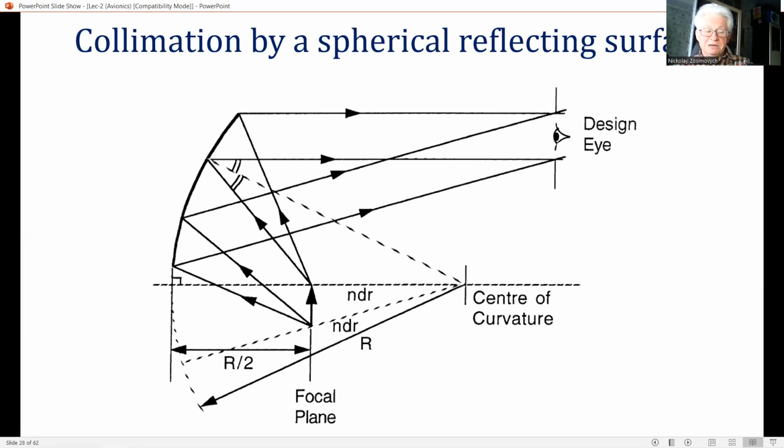The collimating element can also be made much larger than the collimating lens of a refractive HUD within the same cockpit constraint. The IFOV can thus be increased by a factor of 2 or more, and the instantaneous and total FOVs are generally the same, as the pilot is effectively inside the viewing porthole.